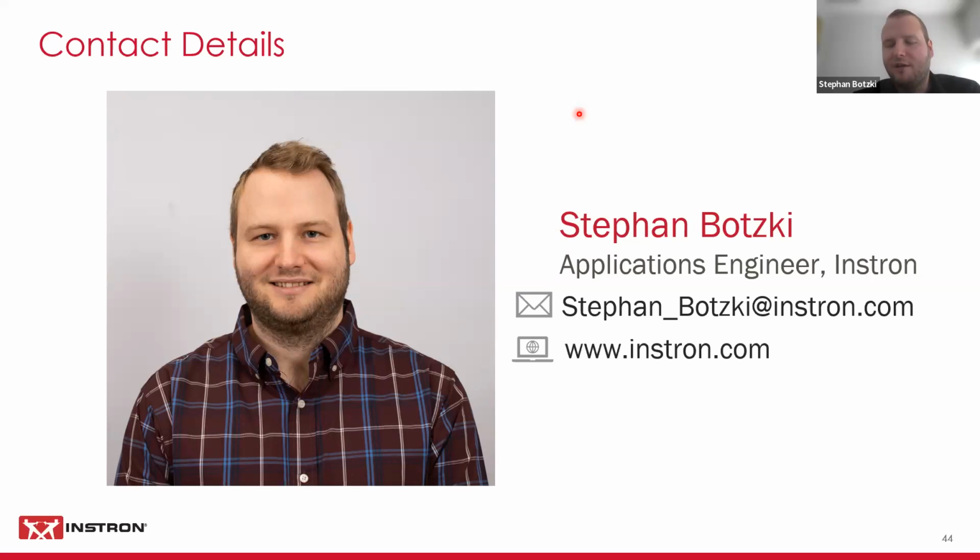And really, you need a modular system where you can make adjustments like you've seen here in my presentation. You can mount things to your grips, you can do different connection types there. If you're just doing tensile right now, in the future you might have to connect something like a DCB test that we've seen for fracture toughness. You can do that with the different interfaces that you can put onto your grips, for example. So before you purchase a machine, make sure that is possible. How modular is the system really?